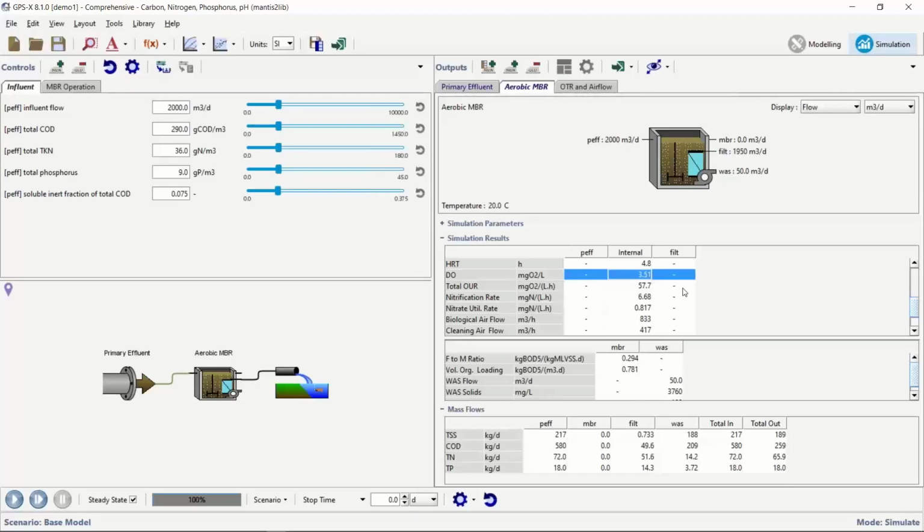If we turn a DO controller on and give it a DO set point of 2 or 3 or whatever number we like, it may behave a little differently than you expect, because it already has this other secondary aeration source that might be providing some of the effort it needs. So it's an interesting aspect of how these systems work when you've got this dual aeration system in the same tank.